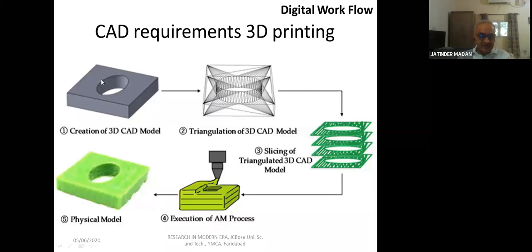Inside, where you have the curved surfaces, you are seeing very small triangles, because curved surfaces need small area triangles for approximation. Otherwise, if you make a big triangle over here, because a triangle is always a flat surface, it will give you a poor approximation of the surface. Here, a big triangle will serve the purpose because this area is flat. We'll come to that also.